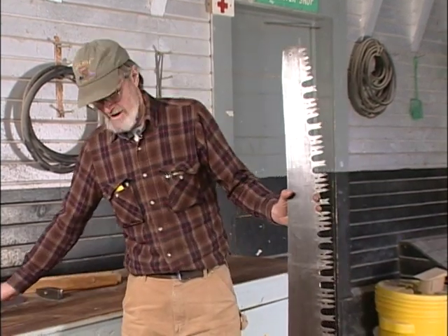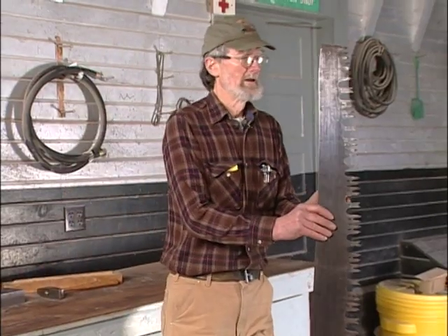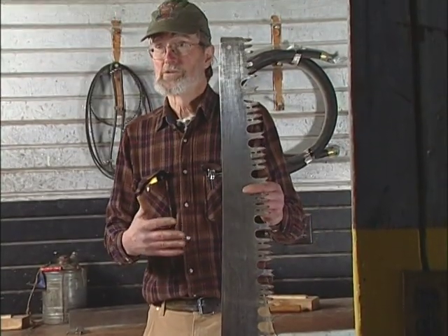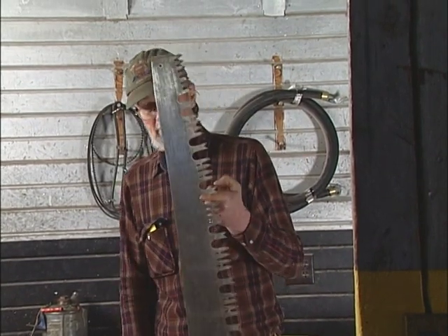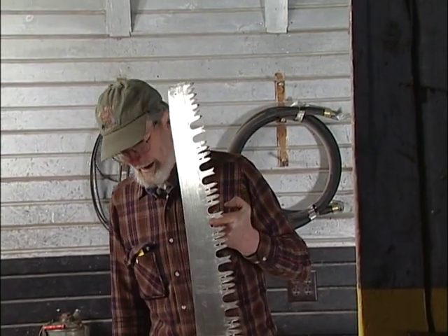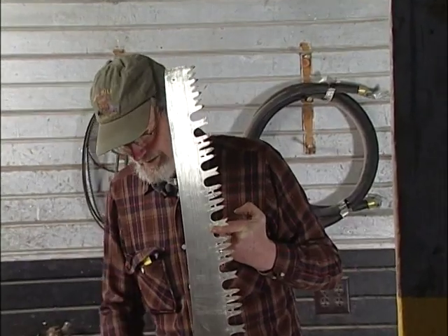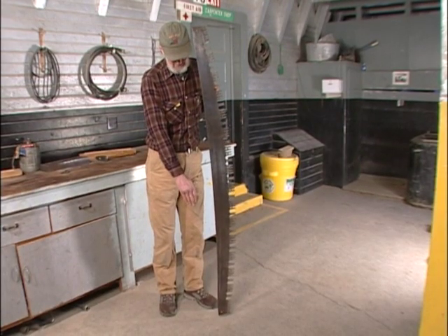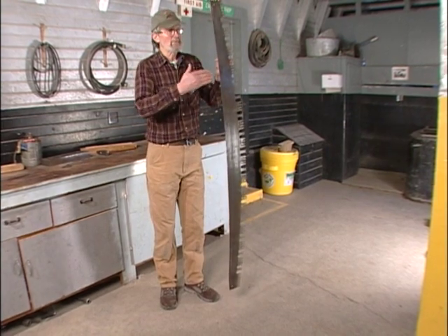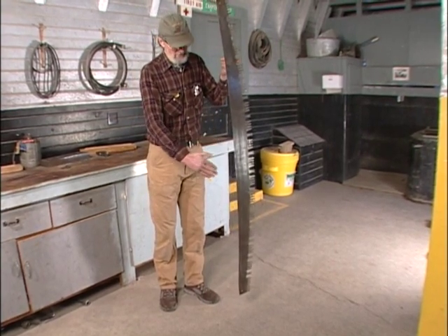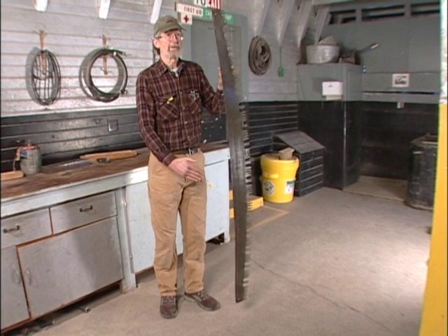Now, normally what I'll do when I'm doing a pre-test or just doing a once-over on a saw to see if it's straight or not, I'll hang it by my finger from a raker and I'll look right down the saw, like this one, looking right down the spine of the saw, or the back of the saw, and that will show up any gradual variations or large bows in it.